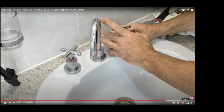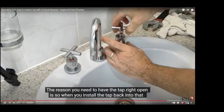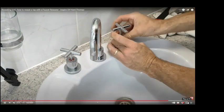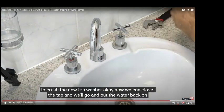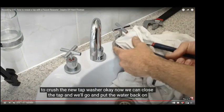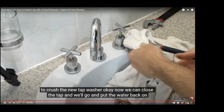The other thing to be careful of, when you tighten it up, you want to make sure the tap's wound fully up. If it's wound down and you tighten up, you just crush the new washer that you just put in there against the seat. You actually damage it or bend the whole spindle. So you wind it fully up, then put it in and tighten it up, and then you can wind it down into the off position.